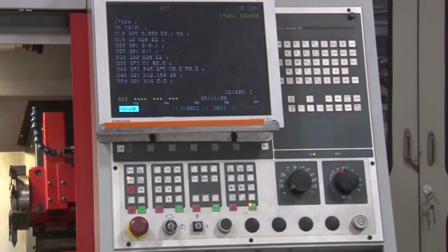And I will repeat once again that the X in the turning is in the vertical direction, to and fro, and the Z is along the axis of the workpiece. So, these are the two axes which are used. Then the feed value has to be given. Then if there is a radius, for example, then the radius has to be given in terms of R, you can see that in the program it is given. So, how this program can be made according to the part that we have to fabricate, this we have shown to you in the simulator.